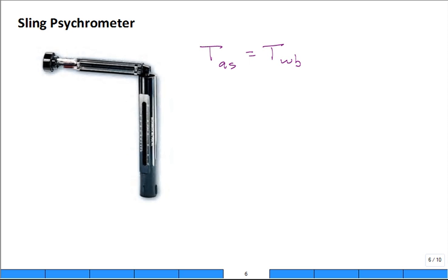And what was the wet bulb? 64. Okay, wet bulb 64, dry bulb, gotta go right to there. Now it's lined up. Now, a little mark, it's a little below 60% relative humidity.